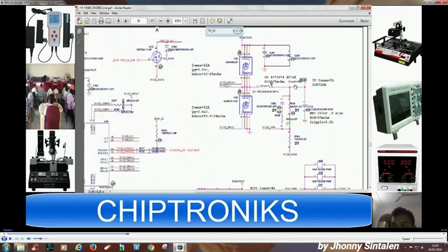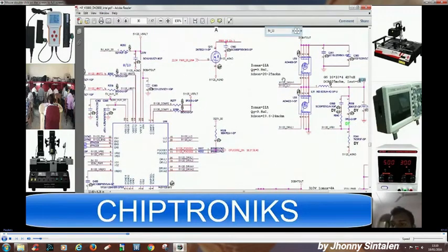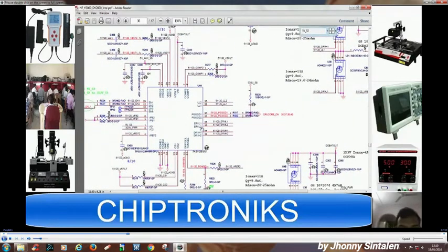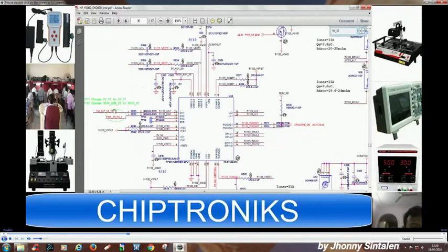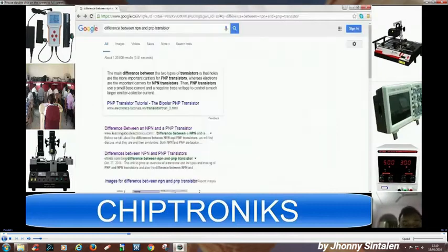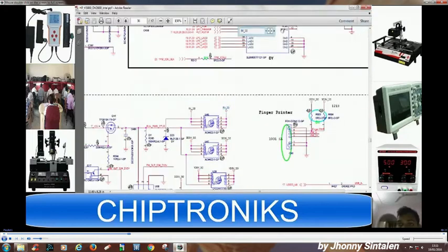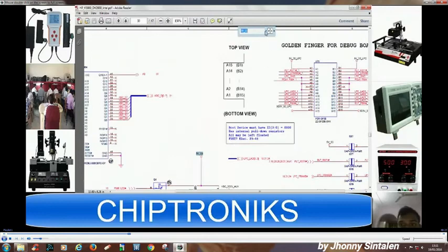You can see this 5V_S3 is generated by the 3V 5V regulator IC by DRVH1 and L1, and DRVH1 will get active only when enable 1 is active, and enable 1 is active when SLPS4 is active. And you can see in this power sequence SLPS4 becomes active after RSM reset, right? After RSM reset. So there is a difference in timing. What I am trying to explain is there is a difference in timing.